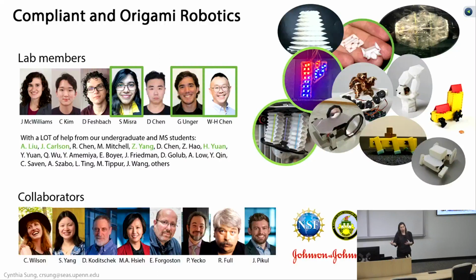So the machined robot's mass varies cubically with the length of the robot, and with an origami structure it varies quadratically. This results in different power requirements and payload capacities. We're trying to do the analysis now to figure out for what sorts of tasks you want to use which type of fabrication approach.